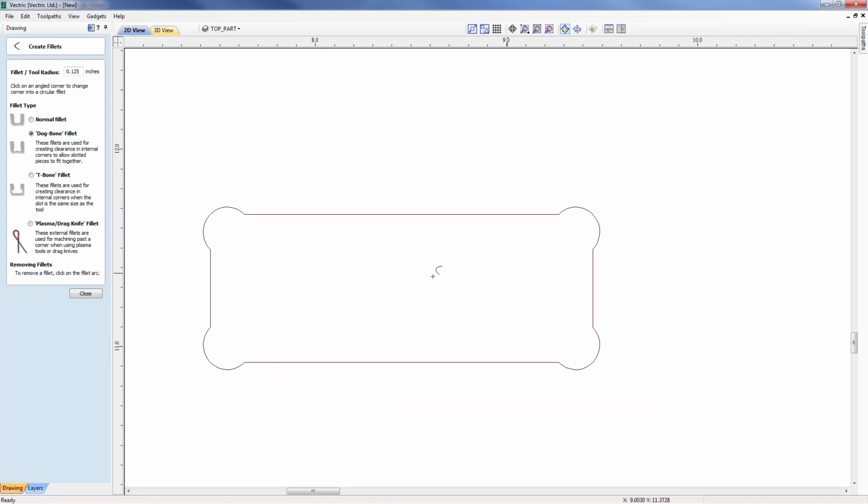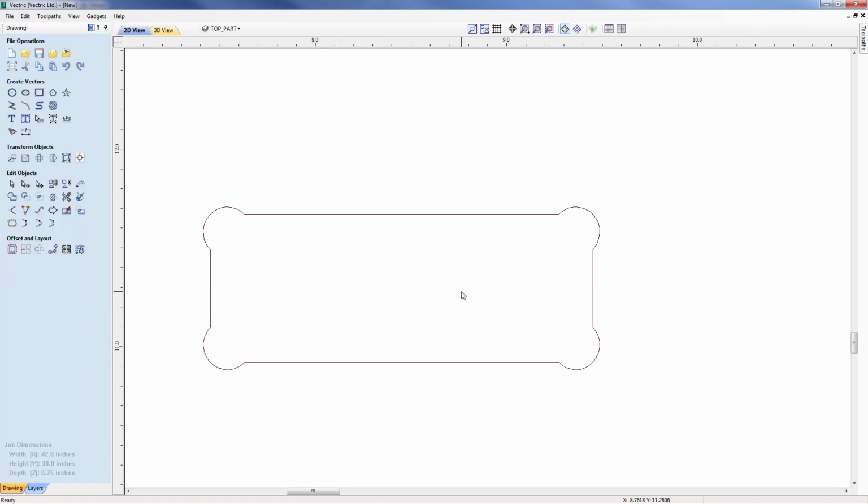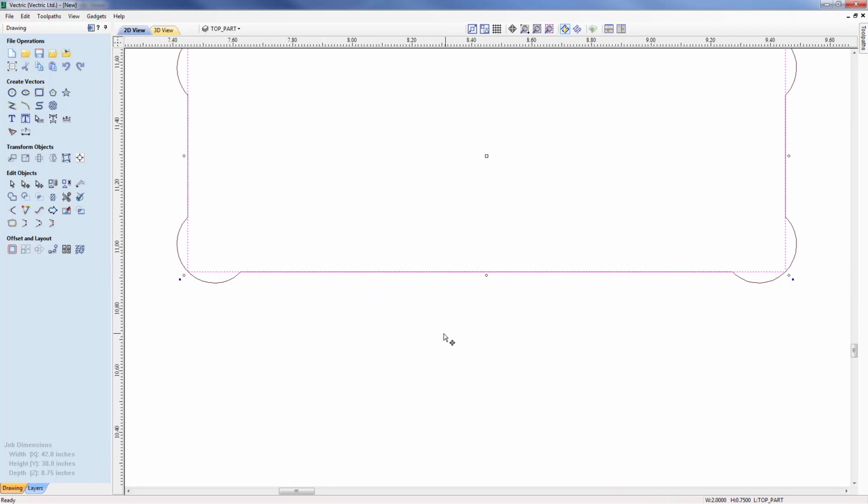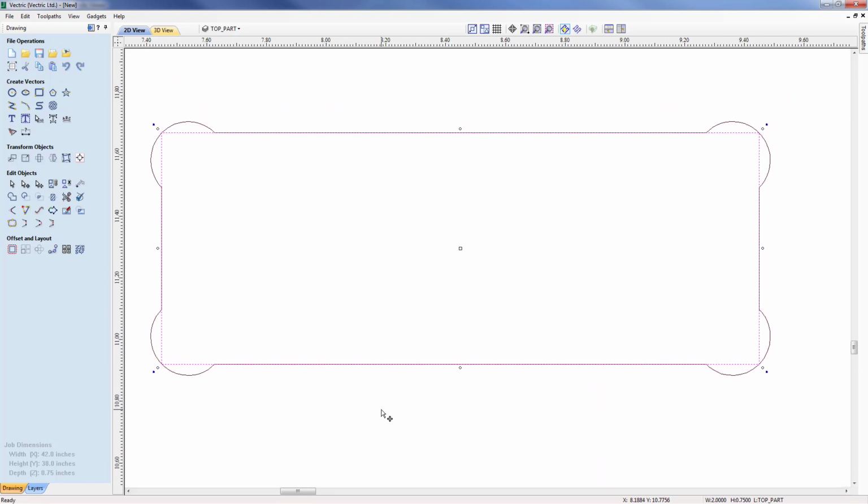Okay, so I've added 4 fillets to this particular mortise. I'm just going to close that out now. We need to check that this will satisfy the tenon going into the mortise. So I'm going to pick that up now and simply put it into transform mode, hold the left hand mouse key on the midpoint and move that across to the midpoint of the mortise, and I can check the corner, and that looks nice. It's going to be a nice snug fit for the tenon inside the mortise.